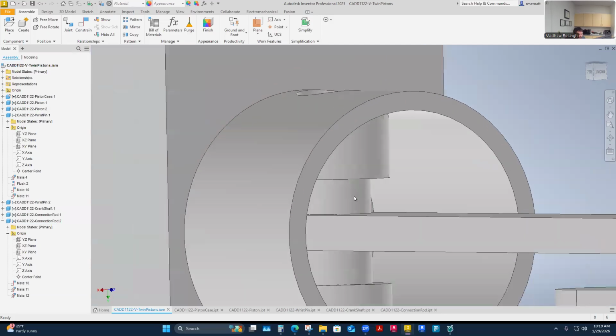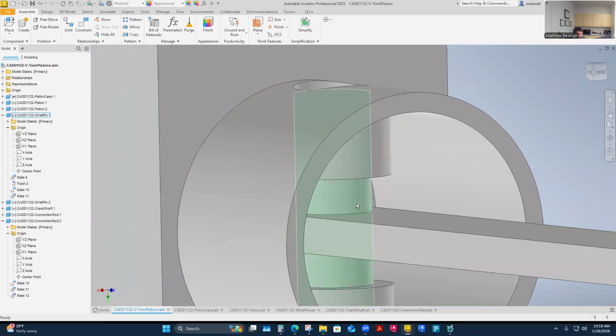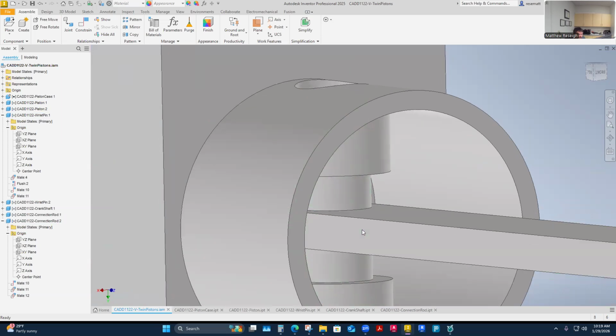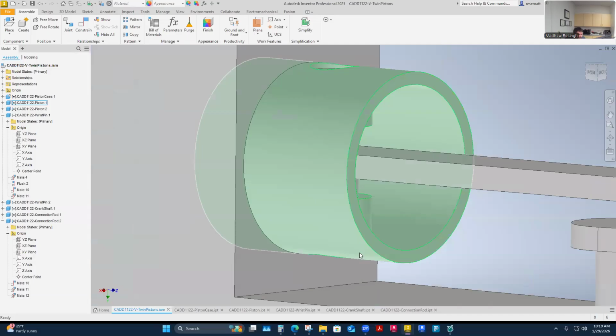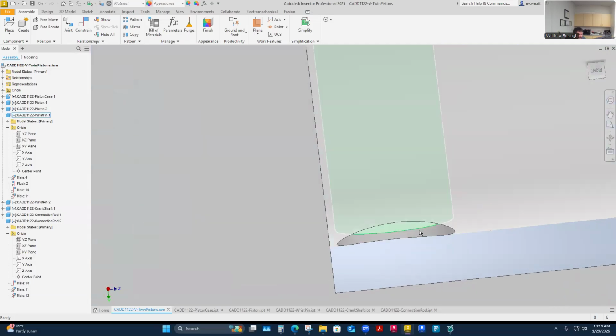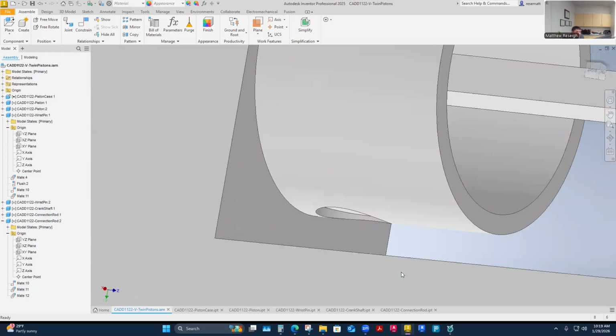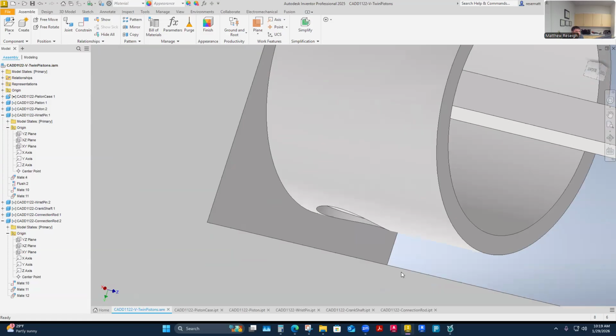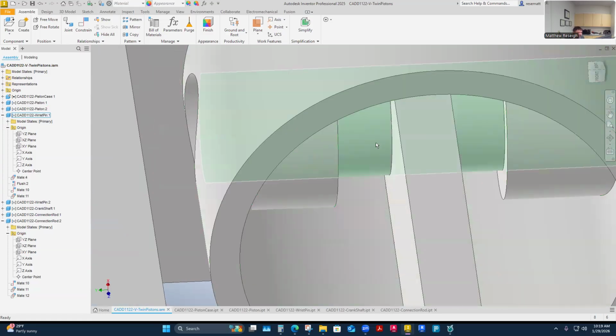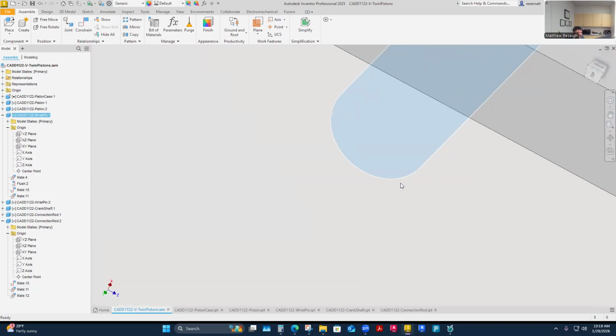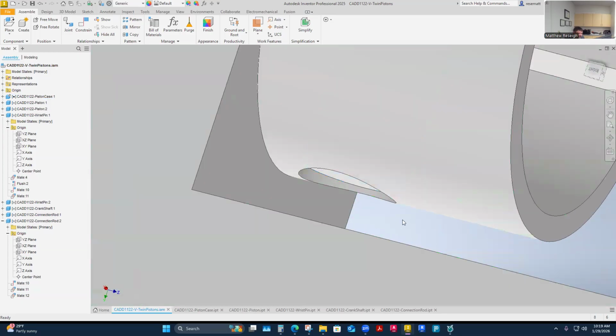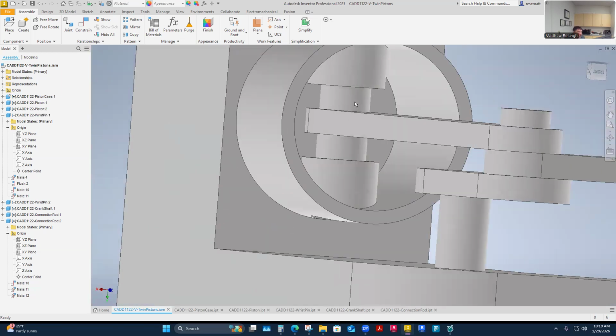You would think that would do it. But even if I control the wrist pin and the connection rod with the fastener and keep that centered, what's going to keep those from falling through? To me, I need a little snap ring in this hole as well to hold the rod from falling out. I don't have that in hand because they didn't have any of them locally. I'll show you what I mean. I kind of need internal and external snap rings. This one I need a fastener that snaps on the wrist pin here, and then I need one that snaps into a hole. Those are called internal and external snap rings. They make them as a standard part, so I was thinking to myself, I'll do that.